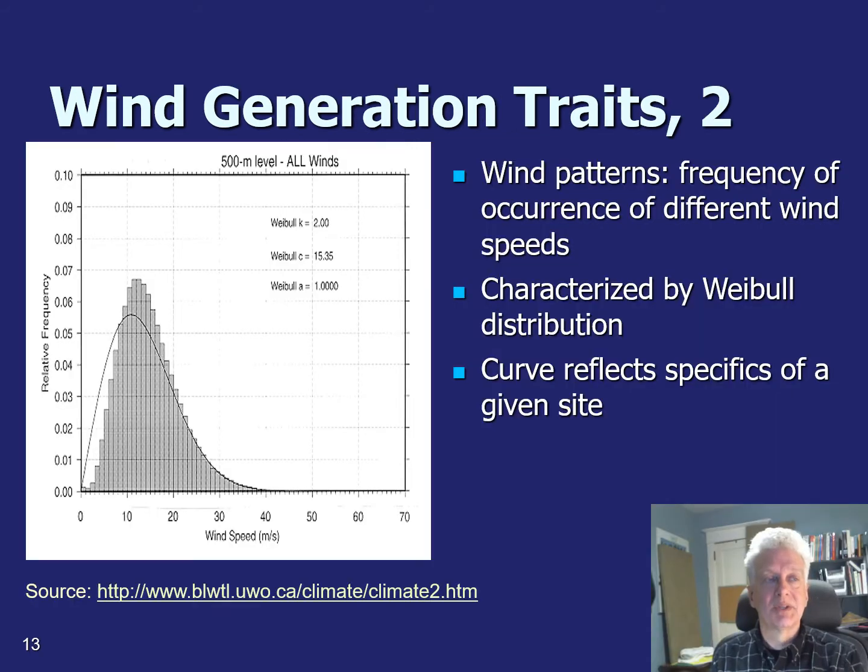Now let's look at the statistical properties of wind. Whatever location you work in, you can set up a wind measurement instrument, an anemometer, and let it run for a good length of time. Often the studies will take 1 or 2 years of data. Then you take the wind speeds that you're seeing there and bin them, and statistically you'll see a nice smoothly varying curve like this that's a little bit like Gaussian, except that it's not symmetrical. The difference is that wind speed is always defined to be positive. So whatever direction it's flowing, you don't count going west as negative or anything like that.